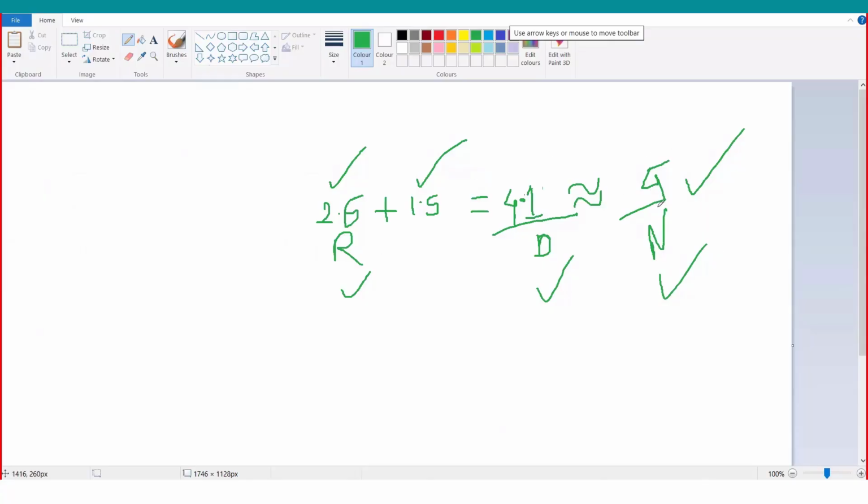So when I have the shell fabricated in the shop, what will be the thickness of that shell? 5 mm. The thickness in new and cold condition means whenever you manufacture it, the thickness available at that particular time. That is called new and cold condition.